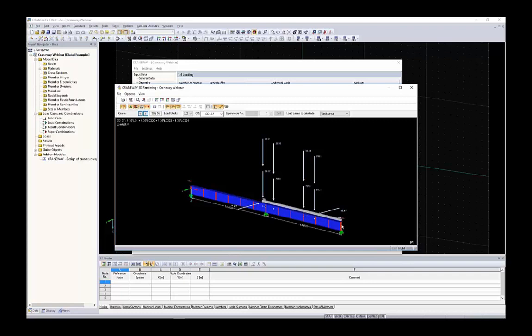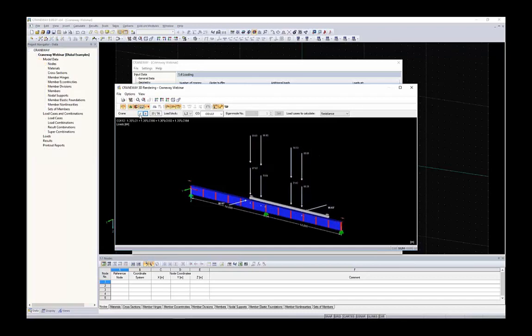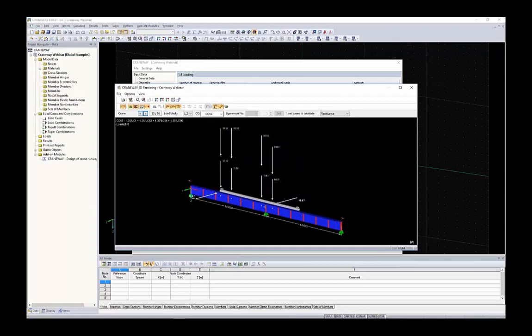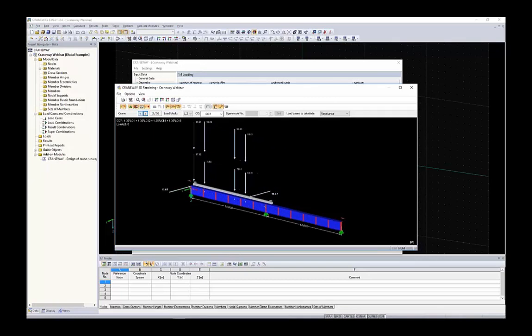The loads are not appearing to be above the support over there. But on the left side, the loads will be above the support at the X location of about 0 meters. So you can check all the load combinations and all the crane positions in the graphic, for the resistance, for fatigue and for deformations.